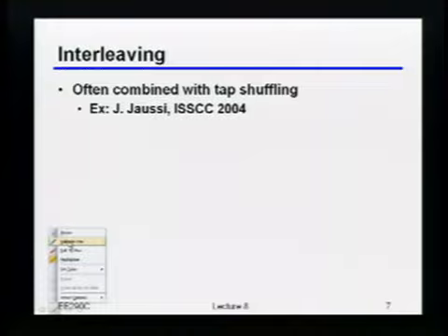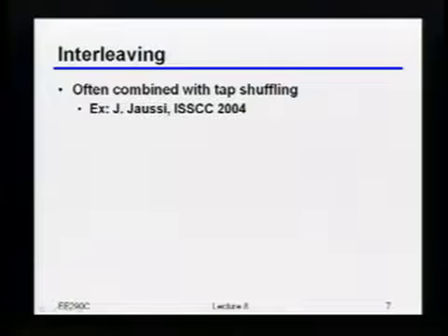So I'm just going to draw it for a 2-tap filter, just because I don't want to do a big complicated drawing. But the idea is very similar, even if you do a larger number of taps and larger ways of interleaving. Okay? So again, just to give you the example, let's say that I take my input here. And the advantage here is that I'm not going to have cascades of sample and holds, but instead I'm just going to have one sample and hold at the very front. Okay?